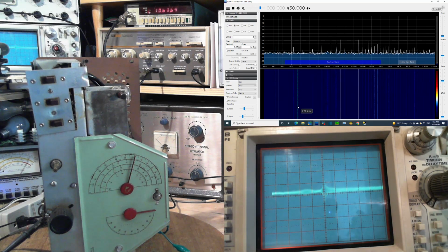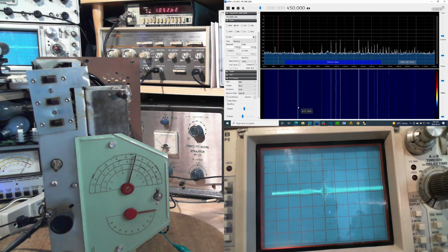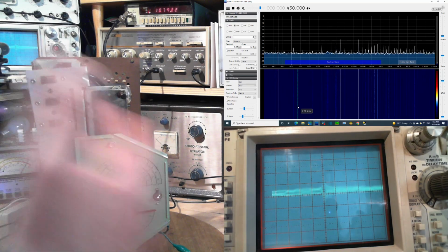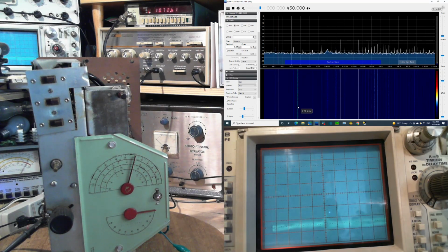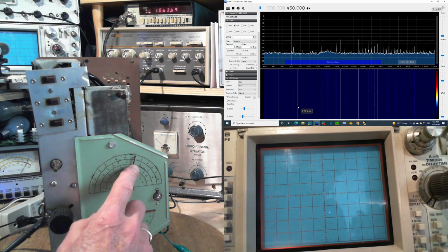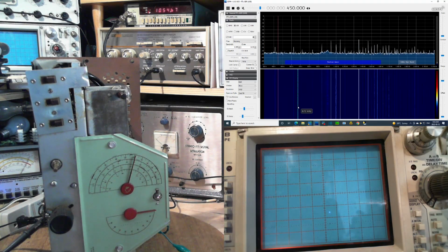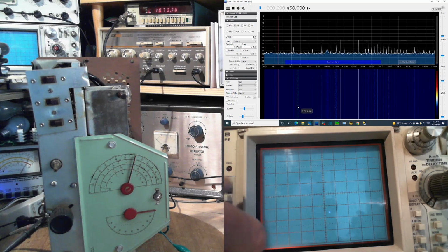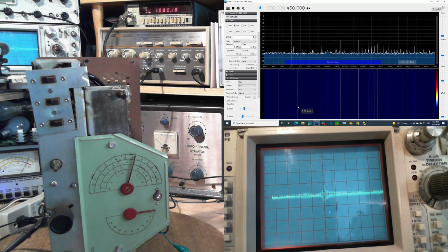Okay. Let's turn it on. Let me turn it on and see what happens. Okay, volume down. Now, we're liable to hear a roar come out of the speaker because the sweep is sweeping past. And the radio's tuned to something, and when the sweep passes by the something, a little bit will come out of the IF. It should show up on the oscilloscope. Where'd it go? Let's put the scope on AC. Scope on AC.